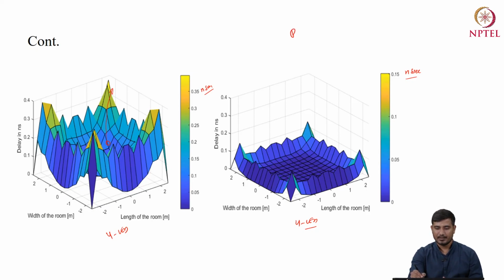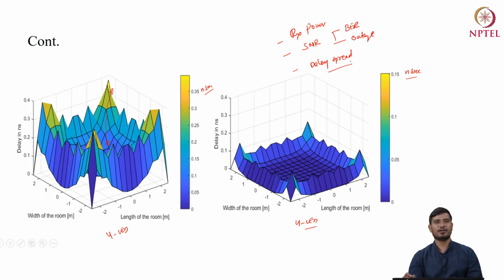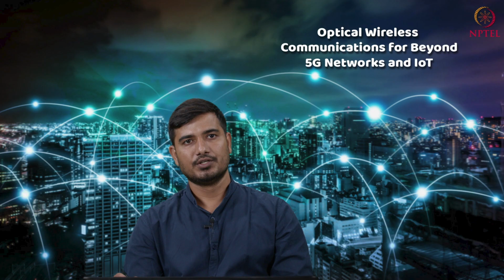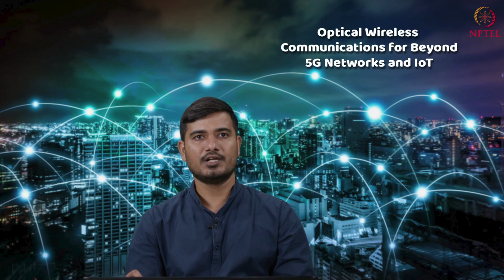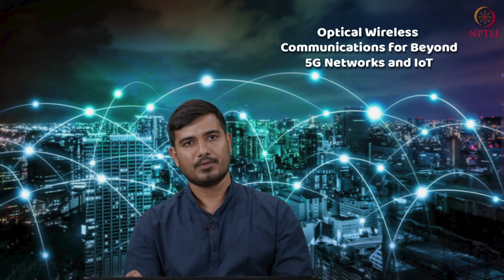calculate this received power, and based on the received power you can calculate the signal to noise ratio, which will help you in plotting the bit error rate or the outage probabilities. And based on that, you can also study the delay spread analysis, which will be helpful in order to analyze your inter-symbol interference. So in this lecture, we have studied how we can simulate this indoor VLC channel model with the help of MATLAB.